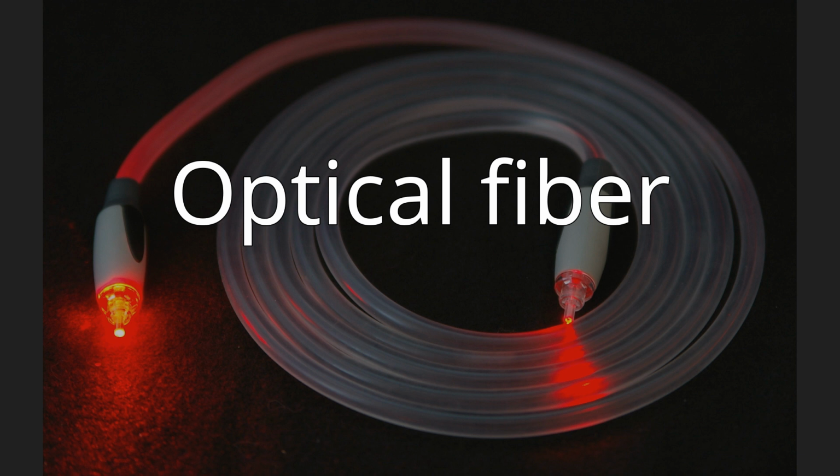For applications that demand a permanent connection, a fusion splice is common. In this technique, an electric arc is used to melt the ends of the fibers together. Another common technique is a mechanical splice, where the ends of the fibers are held in contact by mechanical force. Temporary or semi-permanent connections are made by means of specialized optical fiber connectors.